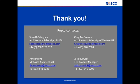And also, it's saying some products for RGBW use one chip. Why do we use two? Again, we think it provides a little bit more latitude when you're tuning the tape, whether it's a specific color or you're trying to saturate or desaturate the color. With a quad chip, in a lot of cases, because you're packing everything into such a tight space, there's an opportunity for a little bit of power bleed through. So even though you're not providing power to the LED chip, the phosphor coating on top might actually get excited a little bit, which impacts your color intensity. So we think by separating out the white, it really gives you much better control and latitude.